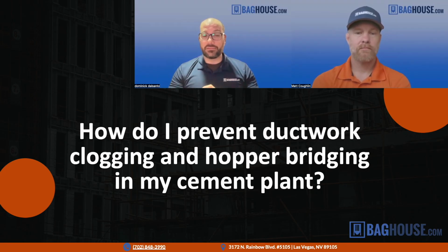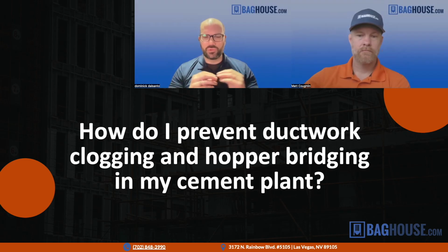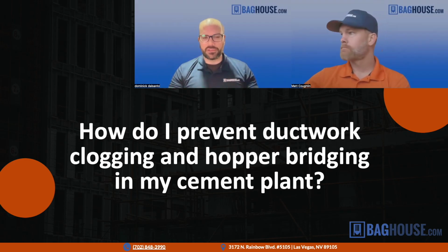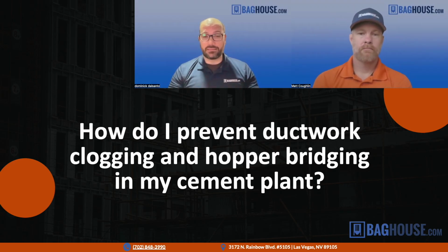That comes down to the kind of dust that you have. Some things are stickier, tend to agglomerate more than others. But a main thing with thinking about the dust collector part of it, big thing is not storing dust in the hopper ever. As soon as dust is blown off the filters, pulsing, whatever dust falls in the hopper should hold that dust basically until the next pulse, and then that's it.